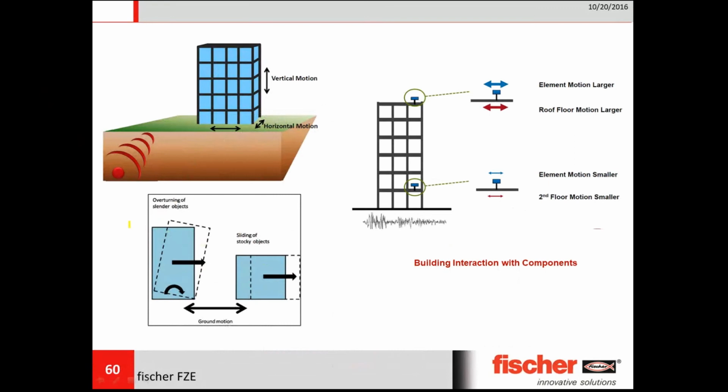If you have a tall building, chances are that the tall building can collapse down. Whereas if you have a massive building like a shopping mall, which is not higher, then chances are that the building itself can slide off during an earthquake.